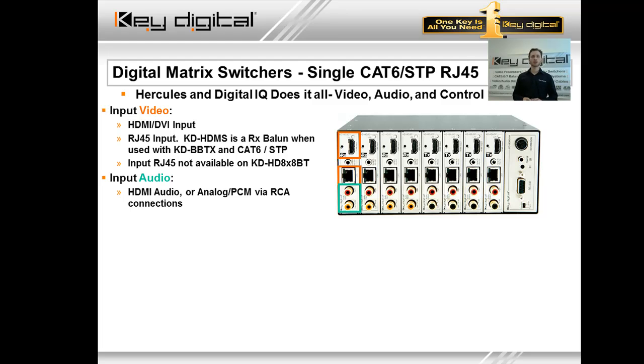You could usually go into that PCM setup menu of that source and tell it, hey, we're doing 2-channel here. And now for your other zones in the system that require 2-channel audio, you're going to select video from the HDMI port, audio from those RCAs through a switching command that we will introduce you to later in this portion of the training. So very big advantage.